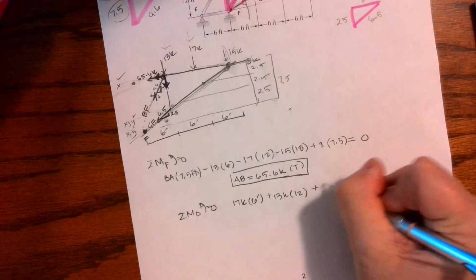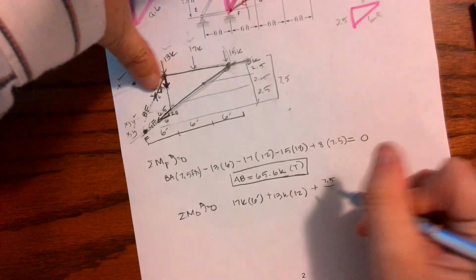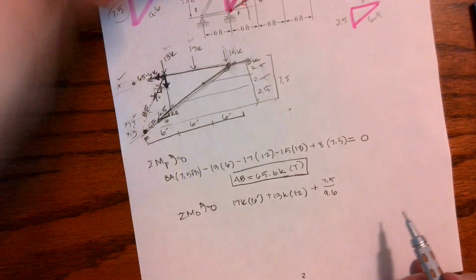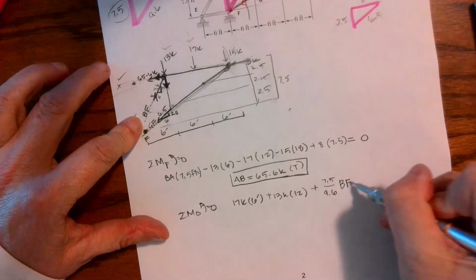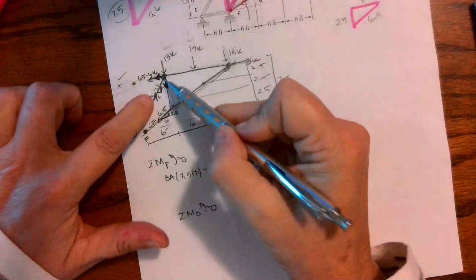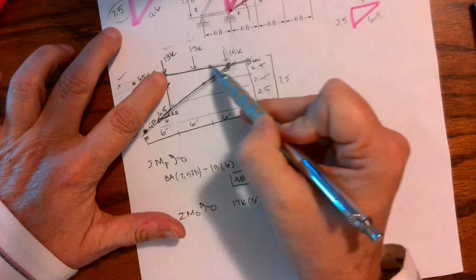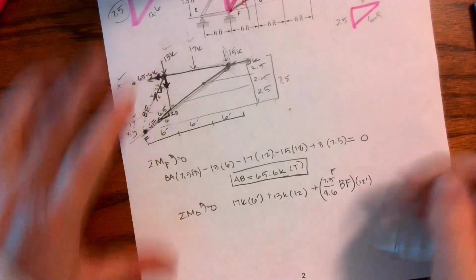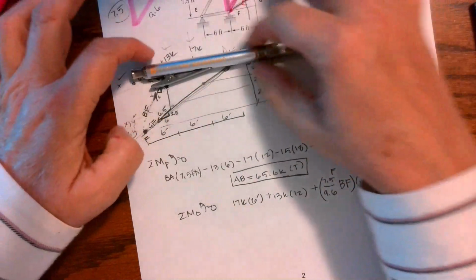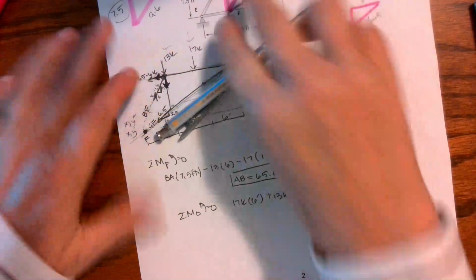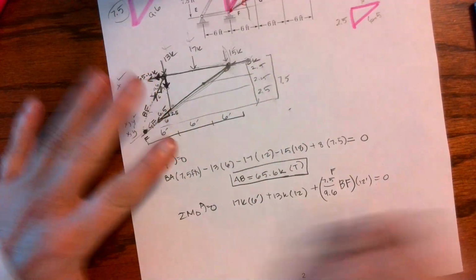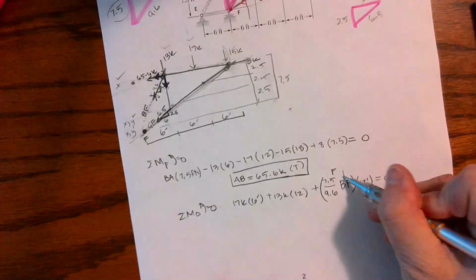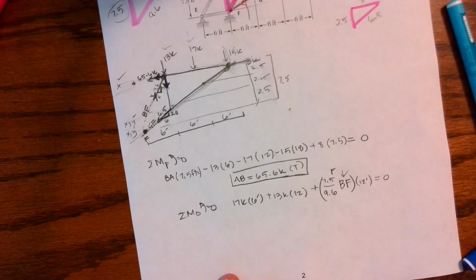It is plus 7.5 divided by 9.6, my hypotenuse, so that's the Y component, 7.5 over 9.6, times BF, okay, so that's the Y component of this vector. It is also 12 feet over, and it is positive because as I'm pushing down, it's causing that positive rotation. This force straight through doesn't matter, so we are left with a pretty short equation right here, and we can directly solve for BF.